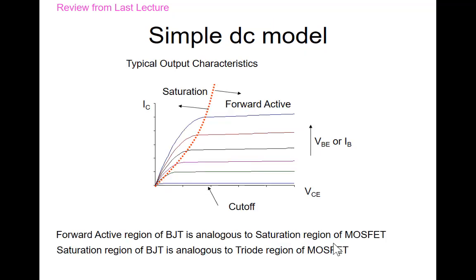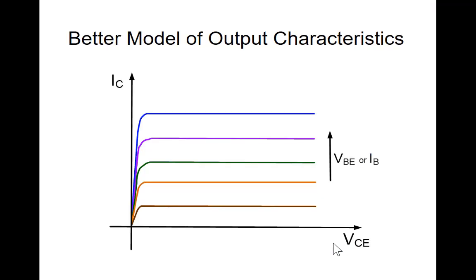And then we said that if you get to lower reverse bias, put less force on those minority carriers when they enter the base region, the efficiency goes down, and the collector current drops down. And those are the regions of operation that we identified for the structure.